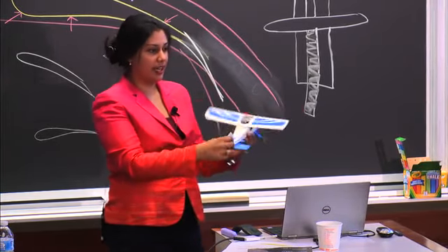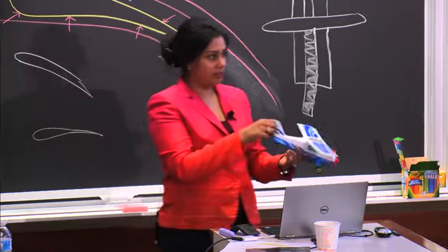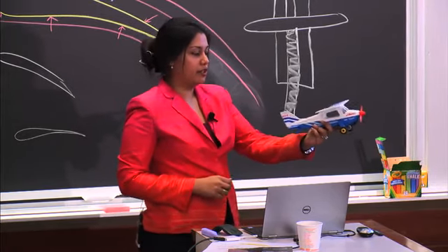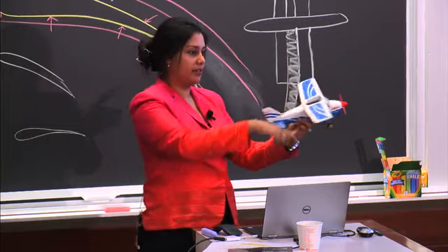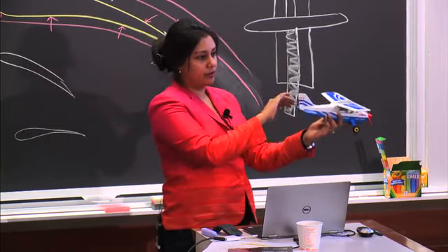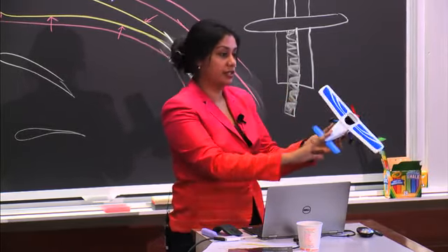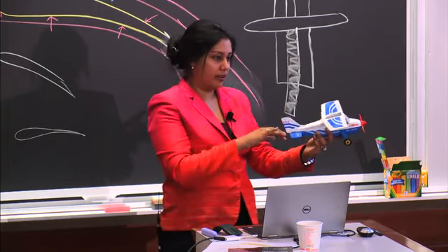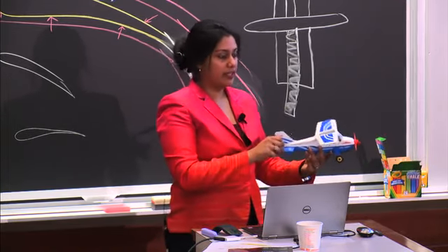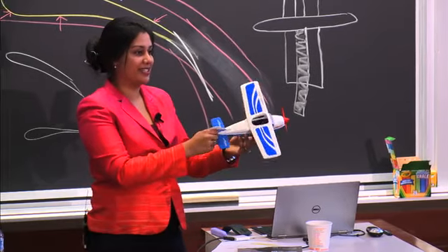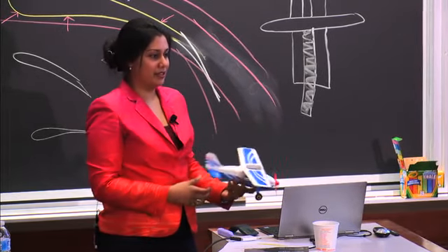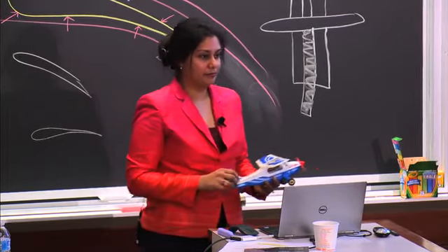These are connected angles, but what we've observed is primarily that the air, when it hits the vertical stabilizer, is the biggest surface pushing it, and the angle that it's at. So if you sum it all together, yes, I'm quite confident you'll get some roll, but the biggest thing that you notice is the yaw.